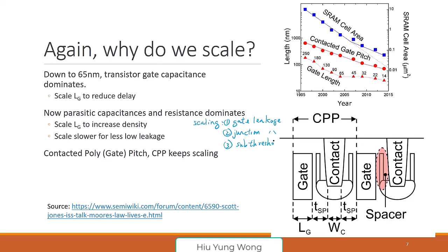Since you answered, can you explain a little bit? What is subthreshold leakage? Basically when the gate voltage is less than the threshold voltage, whatever leakage happens in the transistor is known as subthreshold leakage, because at that time the transistor should not be on. Very good. So we have a transistor, and this is VG smaller than VTH. There's still leakage because the gate cannot control the substrate. So we have this subthreshold leakage.